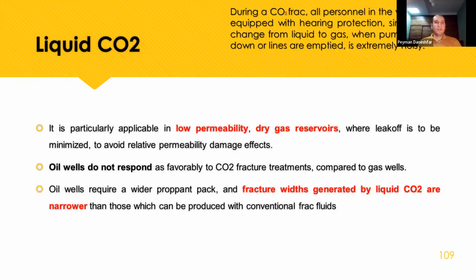Because of the hazards of liquid CO2 pumping, all personnel in the vicinity must be equipped with hearing protection, because when there is a fast change from liquid to gas, when pumps are cooled down or lines are emptied, it's extremely noisy. And we can use liquid CO2 fracturing in a low permeability, dry gas reservoir where leak-off is minimized to avoid the relative permeability damage effect.